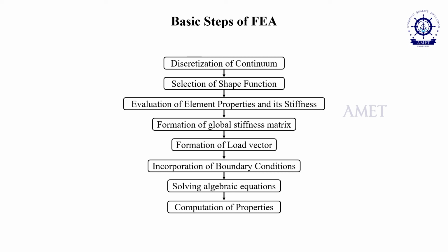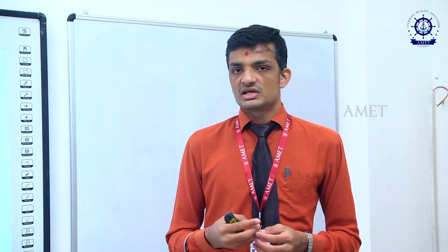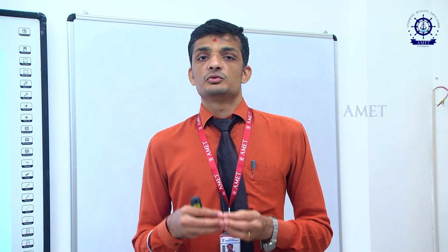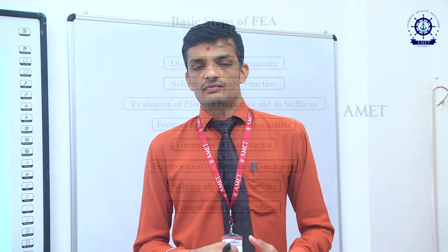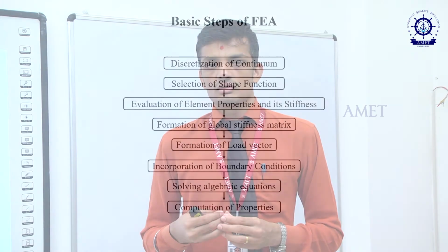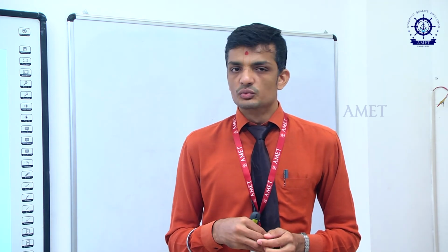So it all starts from the idea of you having a discretization of the continuum. What is a continuum? Any physical problem can be represented as a continuum, and then you break down that continuum into the discrete form. Suppose there is a cantilever beam, you make thousands or hundreds or tens of elements or discretized segments, right? So that's the first step of any numerical approach.